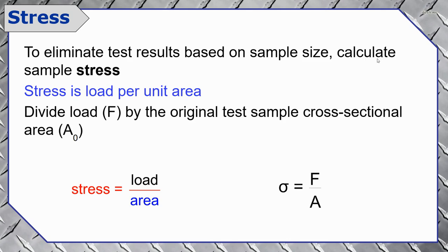So once again, to eliminate test results based on sample size, we calculate the sample stress, or the load per unit area. This is the formula for calculating stress. Stress is equal to the load divided by the area, or the force over the cross-sectional area.